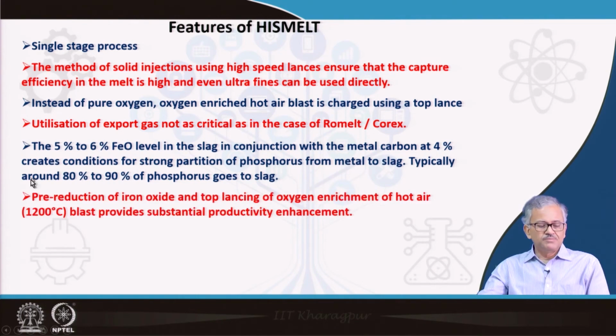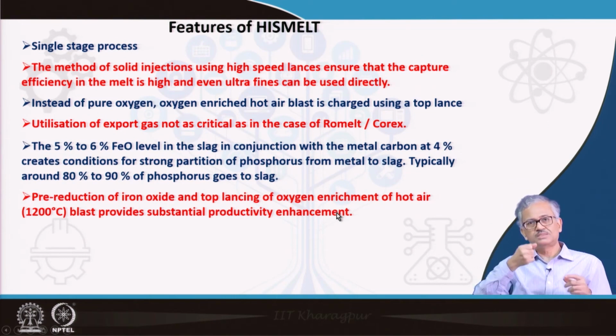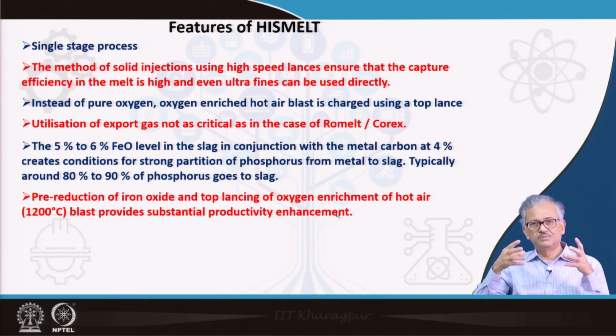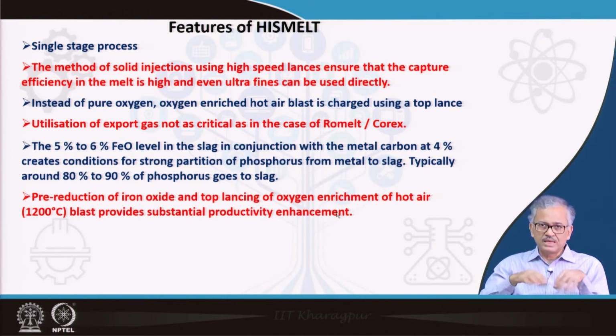Okay. And then pre-reduction of iron oxide, you are doing some pre-reduction and the preheating, and top lancing of oxygen enriched air blast provides substantial productivity enhancement. As I said, if you top lance it, then you also generate a lot of emulsion formation, because when you lance it, the FeO and the carbon react, and emulsification takes place just like in your basic oxygen furnace, LD furnace. So, when emulsification is done, the kinetics become much faster.